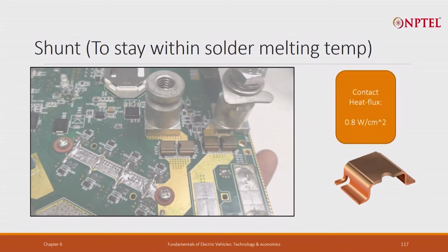There is a concept called heat flux, which is normally a very useful thing to understand how intense the heat is. Heat is measured in watts, but intensity of the heat is the watts divided by the area. Just like pressure is force divided by area. I can press you with my finger and you do not feel any pain, but if I hold a needle in my hand and press you with the same force, you will shriek with pain, because the same force is getting applied in a very small area.